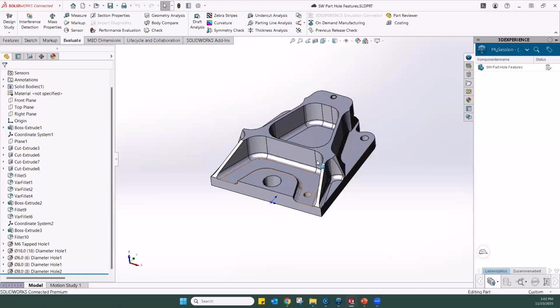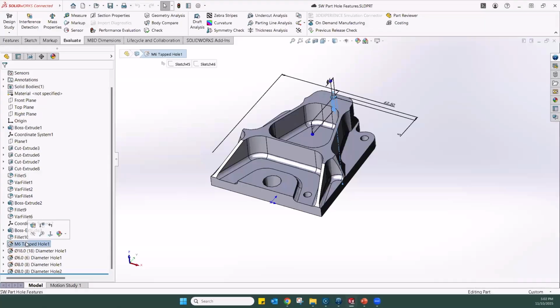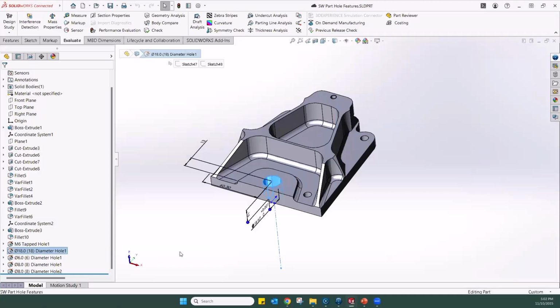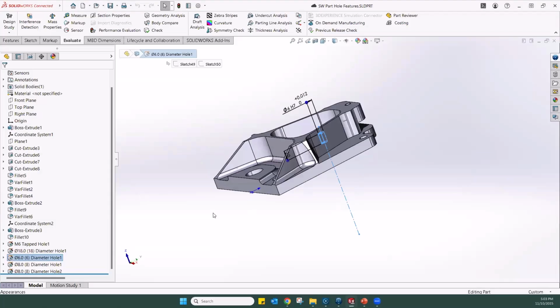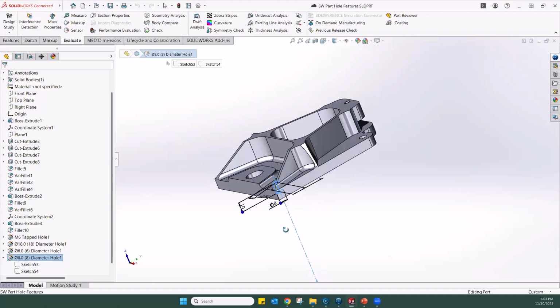You will see here our native SolidWorks part. We have some different geometrical elements, then reference elements, and please remember at the end, we have some hole features. For example, here a thread hole, a tolerance hole H7, a smaller hole, a tolerance hole H7 with the upper and lower tolerance range, and then 2 simple holes.